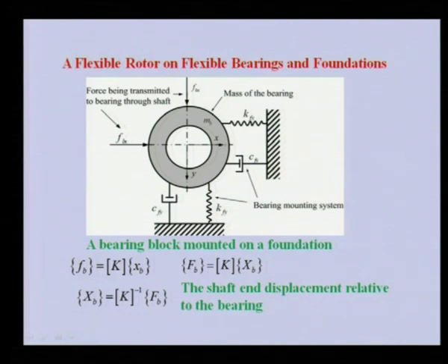Now, earlier we related the bearing force with the bearing displacement with the help of the K matrix. If we convert this into the frequency domain, we will have this expression in which the time dependency terms are not there, and the bearing displacement we can get by inverting the K matrix and multiplying with the bearing force in the frequency domain.